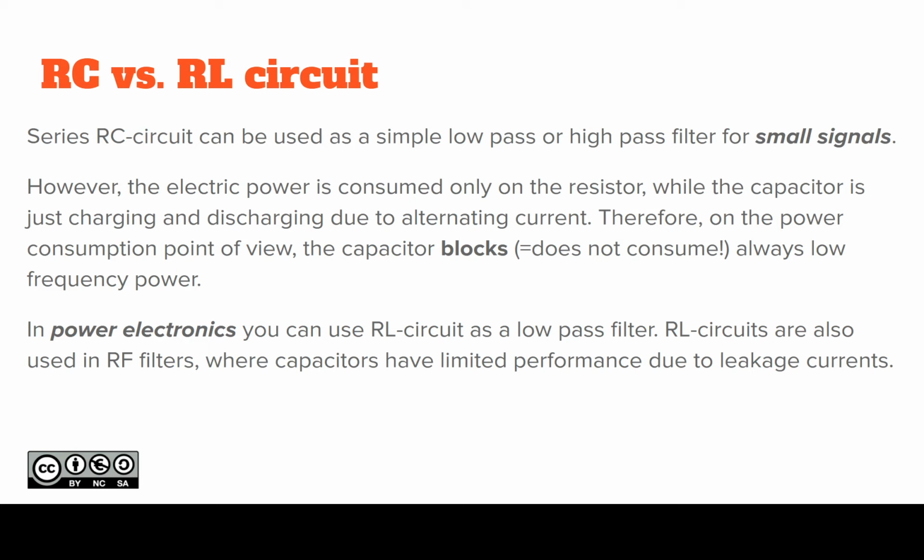For example, switch power supplies are power electronics. And in bigger switch power supplies, they still take quite a lot of space because they have big inductors, meaning they must have thick wire on the coils to withstand the currents flowing through that coil. It takes some space. But anyways, RL circuits are used in power electronics.